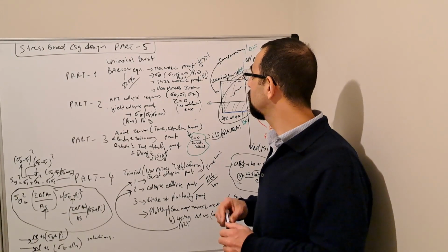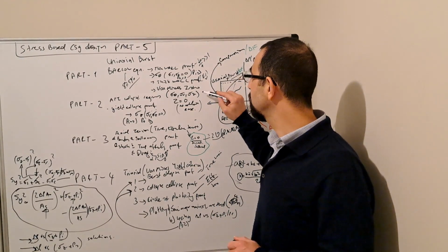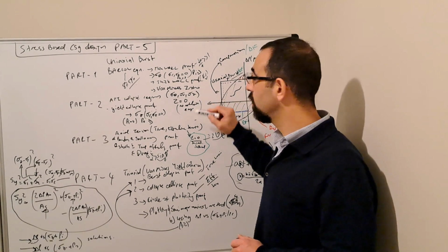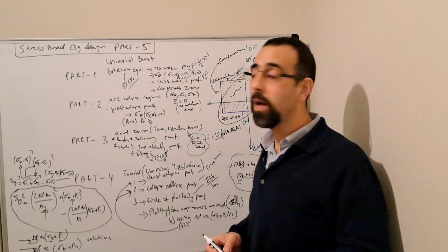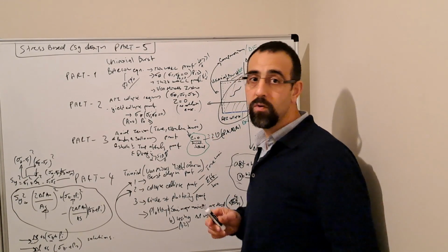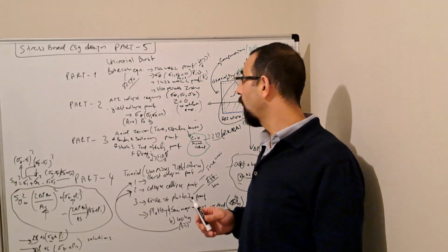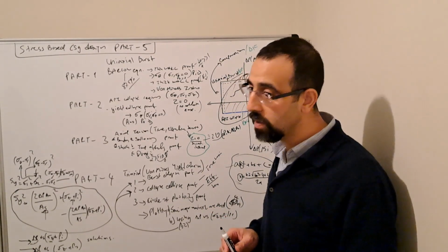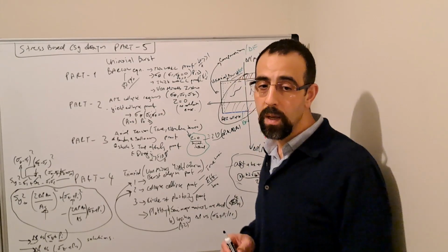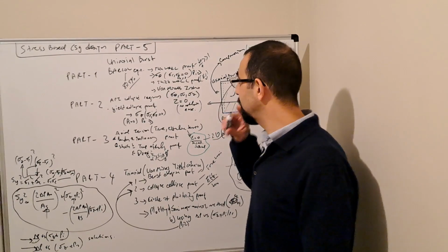Then we talked about the von Mises yield criterion, of course, and said that we will concentrate on a no rotation case. Basically, we are not rotating the casing, where torsional stress is induced, and therefore we have three principal stresses, meaning radial, axial, and tangential stresses.